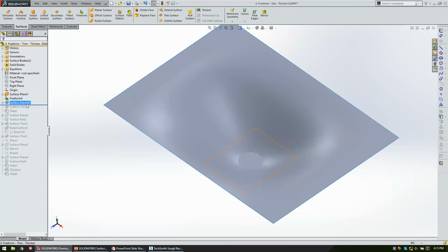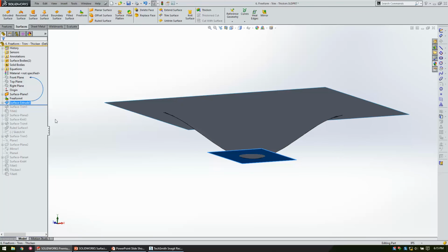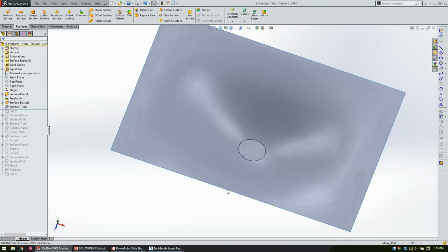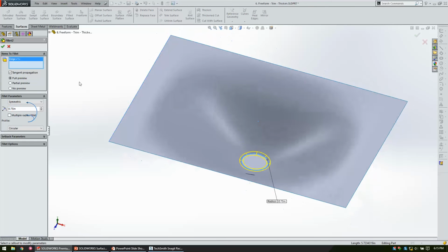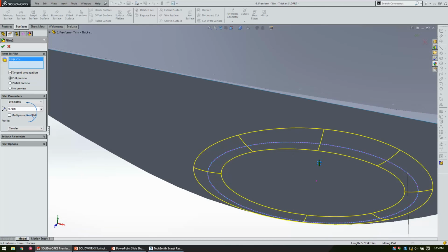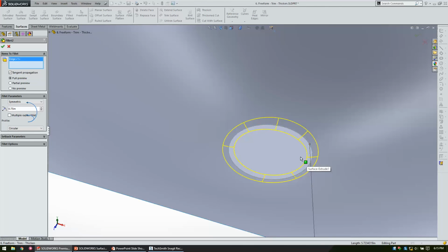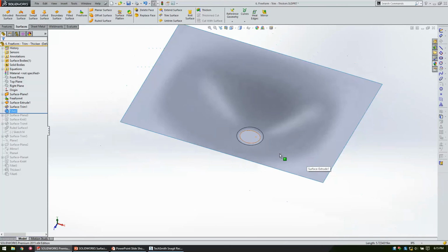So I designed this model quite a while ago for some person that wanted some fancy sink in their house. Here I put a surface on there and then mutually trimmed those together to put a flat for the drain. Filleted that in. So again, like I was saying earlier, the fillet command is very consistent. If you know how to use it today, you know how to use it tomorrow in surfacing. This is a surface body. There is no thickness here whatsoever. I can launch my fillet, put it in there. It'll work perfectly fine. So that's very comforting.